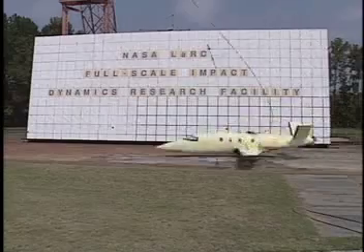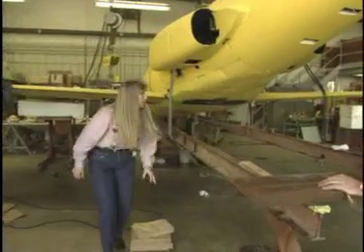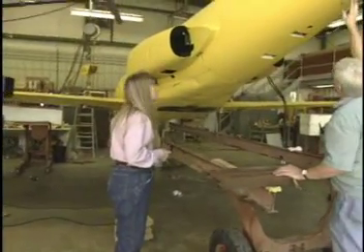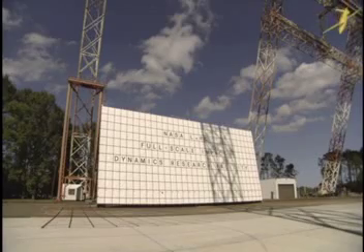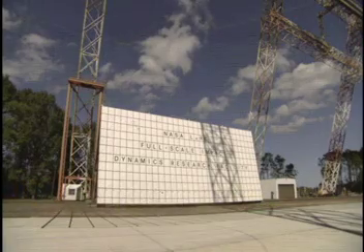Yes, in 1994 we tested a graphite aircraft called the Lear fan. When the original aircraft was released from the gantry, it was extremely rigid and nothing crushed. According to the crash test dummy data we collected, only one of the 6 passengers survived. So we used that data to design a new energy-absorbing or crushable subfloor. It would be like putting a bumper under the floor. Then we built and tested small sections of different subfloor designs until we had the best design. A second Lear fan was modified by installing the newly designed subfloor and tested. The results showed that the new subfloor improved the Lear fan's crashworthiness by reducing the forces on the passengers.